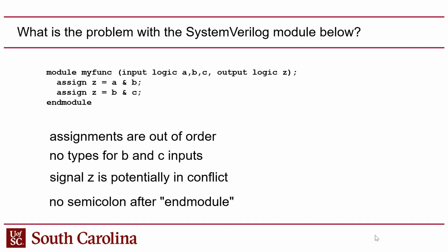I mostly deal with the synthesizable Verilog, right? Which is nice because it kind of limits it to a fairly simple language if you're only talking about what you can convert to hardware. It's basically just assign statements, structural Verilog, and the always block, right? That's pretty much it. And so that's what we focused on in this class.